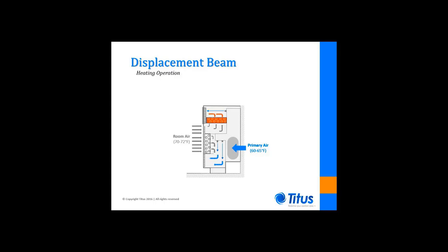As its temperature is still slightly lower than the room, the primary room air mixture from the lower mixing plenum still discharges in a low-velocity displacement manner. The mixture of heated room air and primary air in the upper section is discharged vertically up the outer wall. The heating coil within the TAO units can supply limited, unoccupied heating even when the air handling unit remains off.